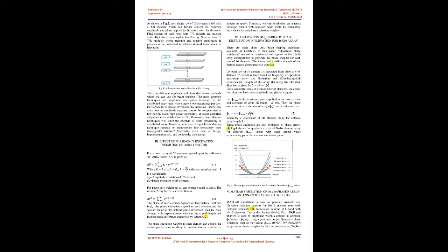For AZ_BW of 2° to 5°, the dwell time available at 12 RPM is in the range of 26 to 70 milliseconds. A very little time of 1.3 to 3.5 milliseconds is available to switch multiple high-power narrow beams to meet the required vertical coverage. Considering the scanning and switching time constraints, it is advantageous to have a broadened beam on transmit rather than multiple switchable beams. On receive, multiple beams can be formed using either analog or digital beam forming based on system requirement.